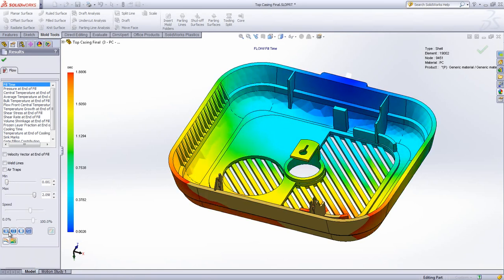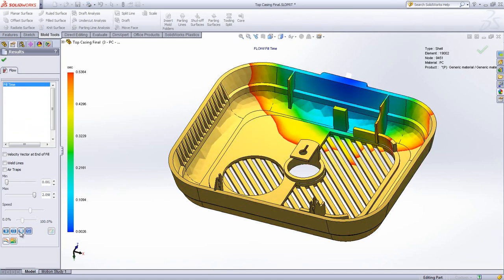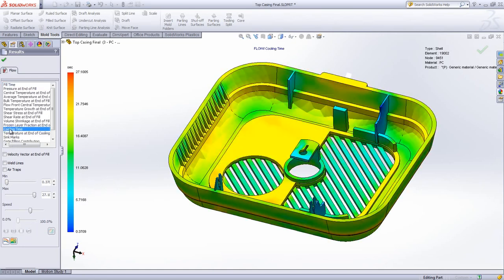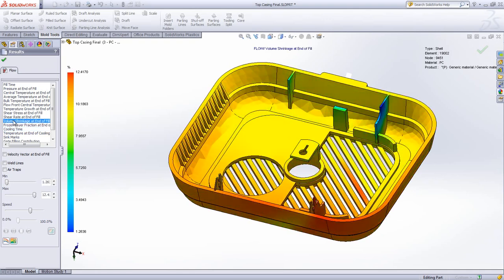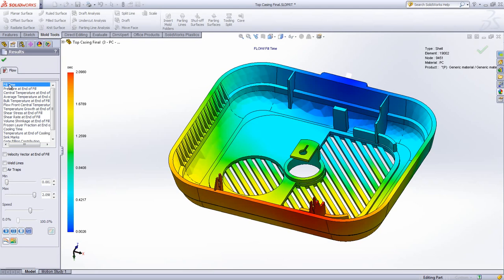The cooling time, which is the time it takes for the part to cool to a temperature for which it is safe to eject the part, is reduced significantly by more than 50%. It's because the wall thickness usually drives the cooling time, and the cooling time is often about 70% on average of the overall injection molding cycle time. This means that by improving the geometry of your model, you can reduce the cycle time and also lower the price per part.